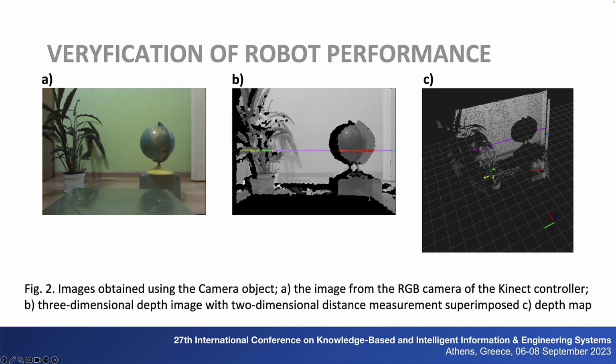The topic camera depth image raw containing the data from the depth sensor was selected in the subscribed topic field in the object settings. Laser scan, visualization of distance measurement. The topic scan published by the depth image to LaserScan was selected in the subscribed topic field. The measurement is represented by points of different color. Closer objects turn red, those far away, towards the violet.